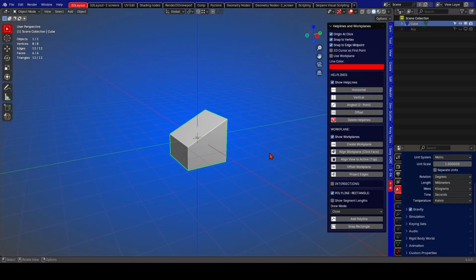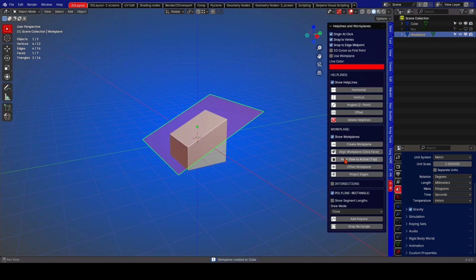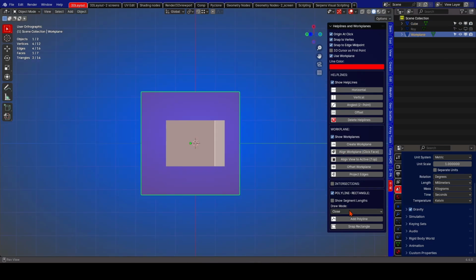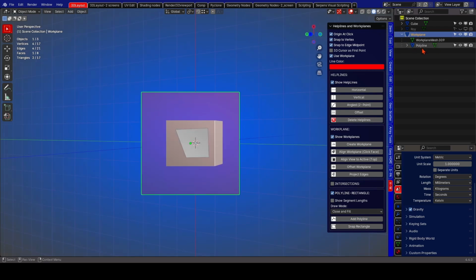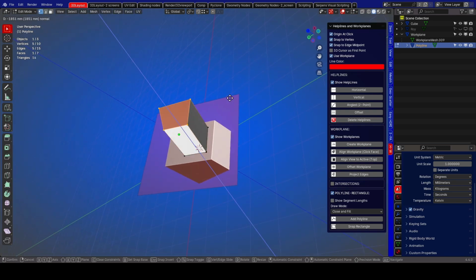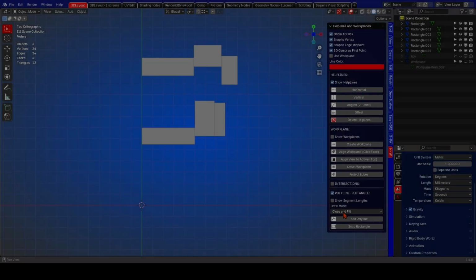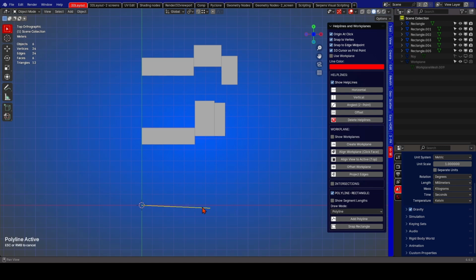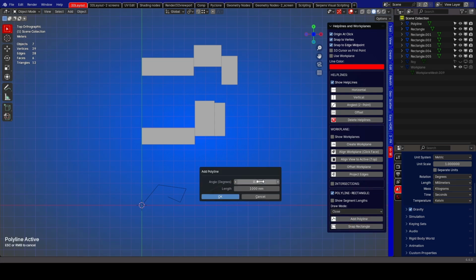The polyline can also be used in combination with the workplane. Just select the workplane first and select the type of polyline. After that, you can start drawing. There are 3 types of polyline. The open type, to just draw a continuous line, with the possibility to add a length and angle, if Shift and left mouse is pressed after a point is picked.